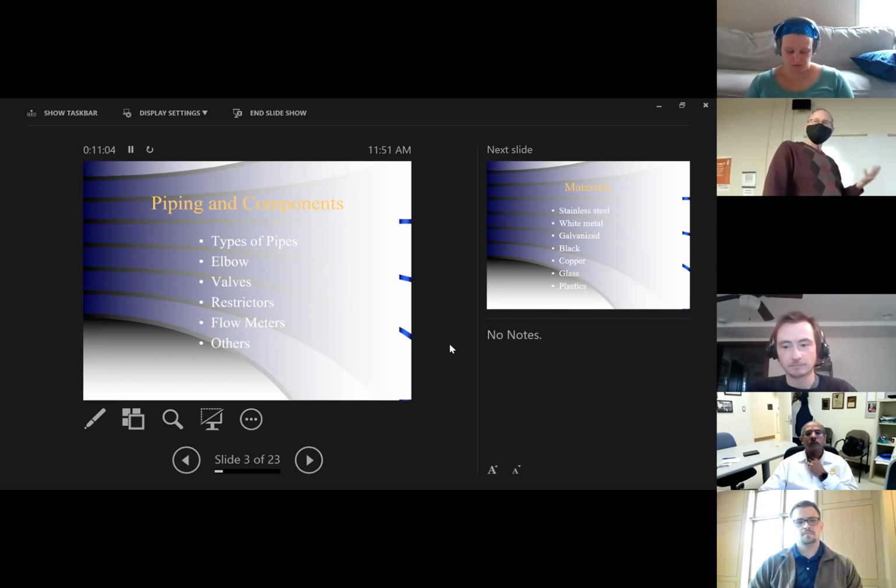But if you're involved with designing or putting together a plant, you can buy 30 and 60-degree elbows off the shelf. But if you need others, you're going to have to make sure that you've got a good stainless steel fabricating company that is doing the work for you, so they can actually bend the pipes to meet the elbow requirements that you have coming.